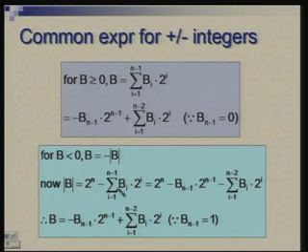Now, this summation can be broken up. We take n minus 2 terms, keep them inside the summation and bring out the one which corresponds to the sign bit. Now, b_(n-1) is 1 in this case. So this thing is nothing but 2 raised to power n minus 2 raised to power n minus 1.